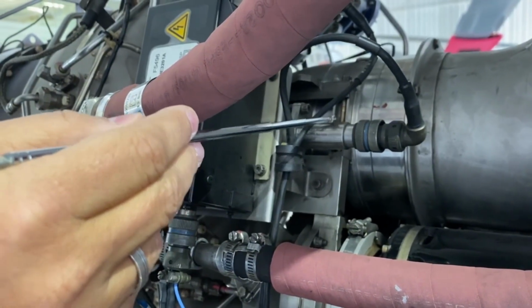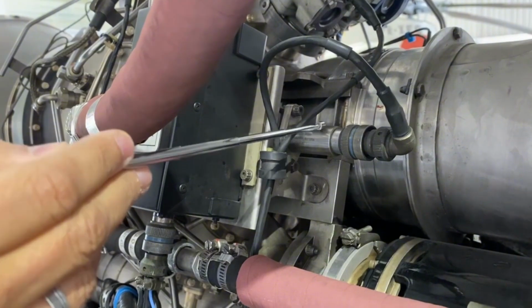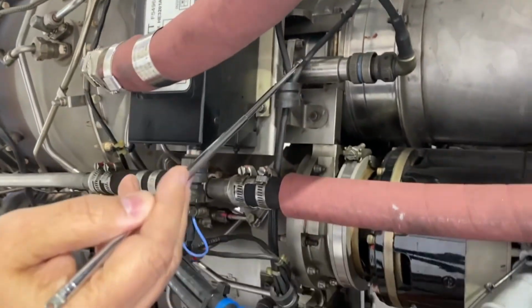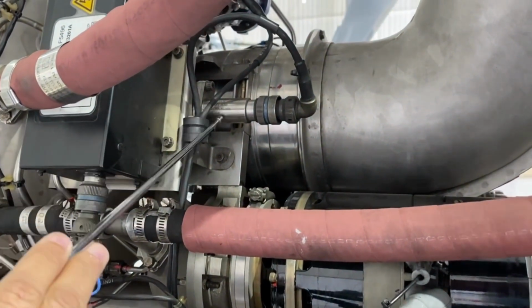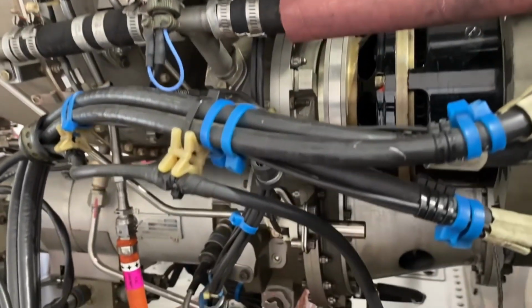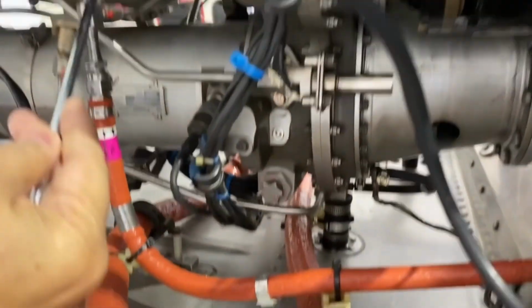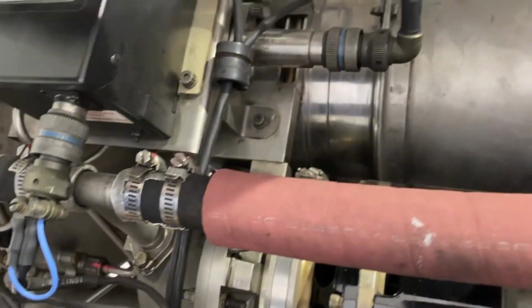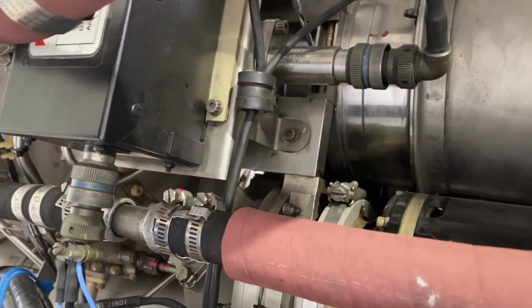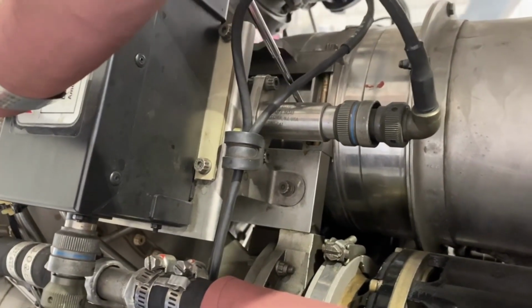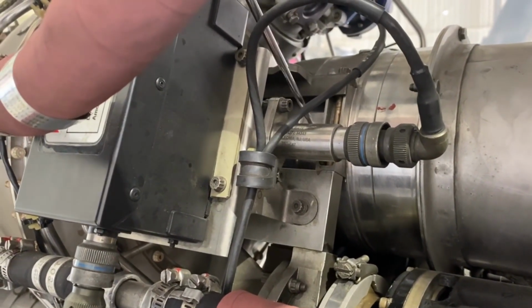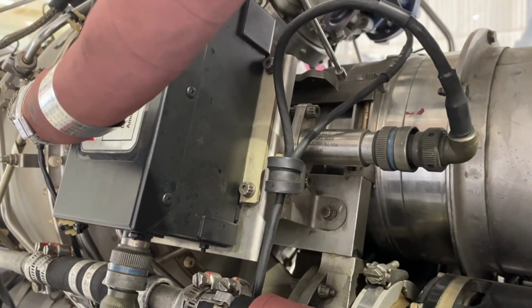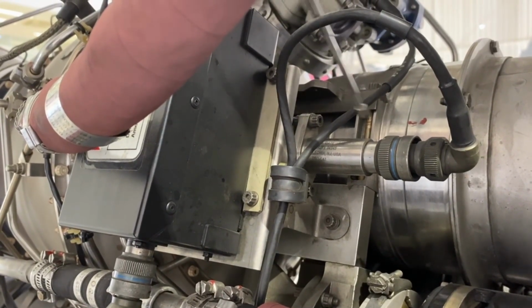This other transmitter is called the P3 transmitter. It informs the FADEC of the pressure in the compressor at station 3. So if you look right here, there is a specific pipe. It comes all the way down here underneath the assembly to pick up the P3 signal. It picks up that P3 signal down here in this section, where the pipe is. The pressure transmitter located right here continuously provides data to the FADEC system regarding the current P3 air pressure levels, so that P4 never becomes greater than P3. P3 must always remain greater than P4 in order to ensure that the engine does not experience a compressor stall. That is the role of the P3 transmitter.